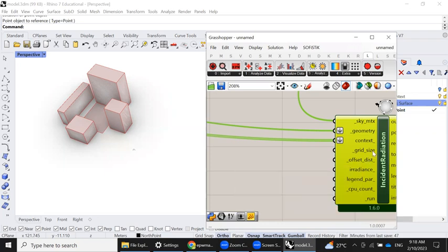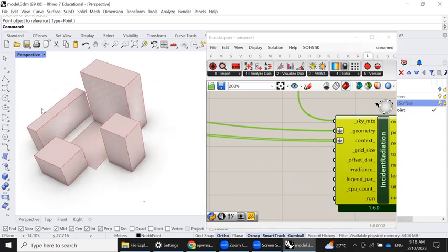So what should our grid size be? The units that I've set this up in, in fact, for most analysis, you should always use meters instead of mm, because by default they are set to meters. So it will think that your 3D file is all in meters.